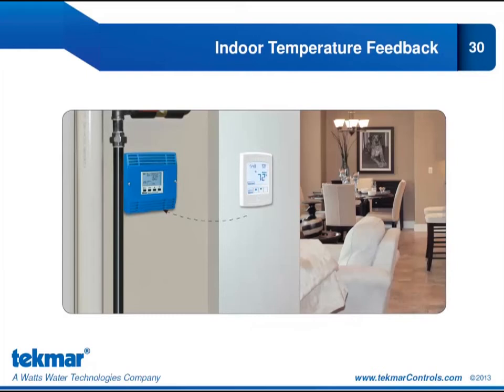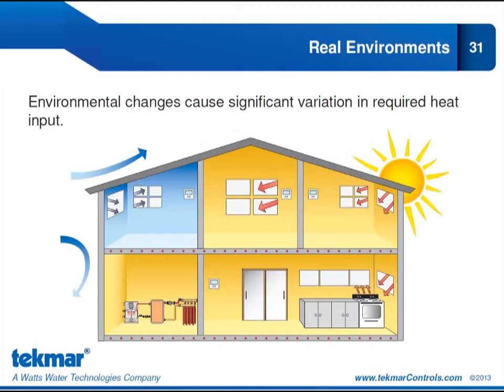Starting with indoor temperature feedback. Now, a lot of you have probably heard of indoor temperature feedback as it relates to our boiler controls, and the same theory applies to our heat pump controls and our zone controls. We can use the communication from the zone control to the system control to further reduce that entering load water temperature whenever possible. And the reason this is significant is because environmental changes cause significant variation in the required heat input. So not all spaces can be treated equally.